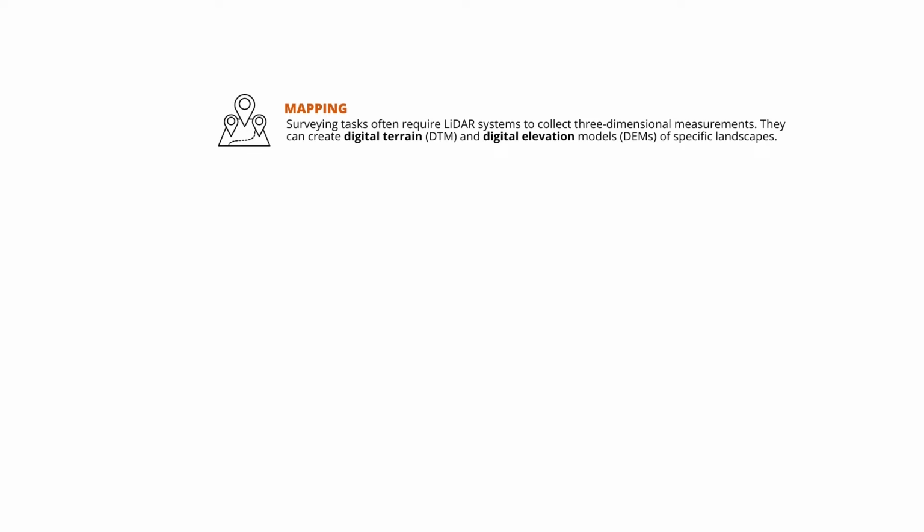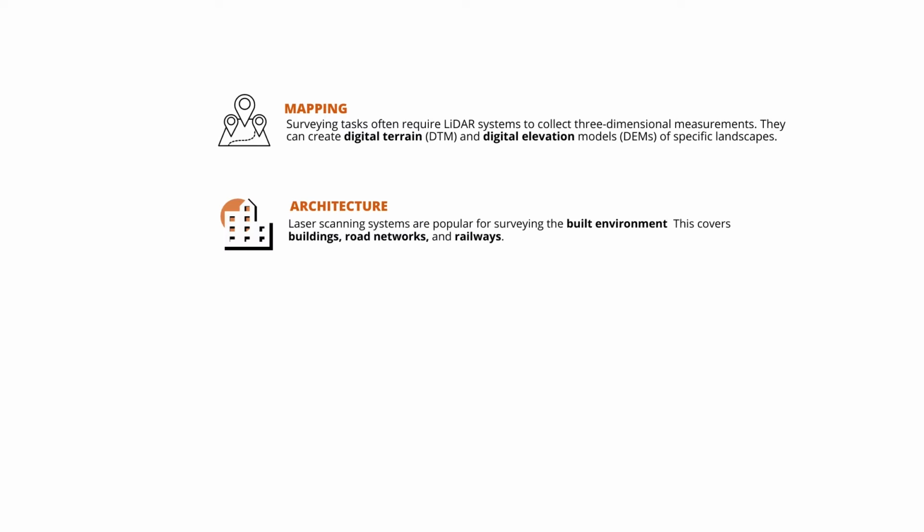Fields of usage. Mapping. Surveying tasks often require LIDAR systems to collect three-dimensional measurements. They can create a digital terrain model, DTM, and digital elevation models, DEM, of a specific landscape. Architecture. Laser scanning systems are popular for surveying the built environment. This covers buildings, road networks, and railways.